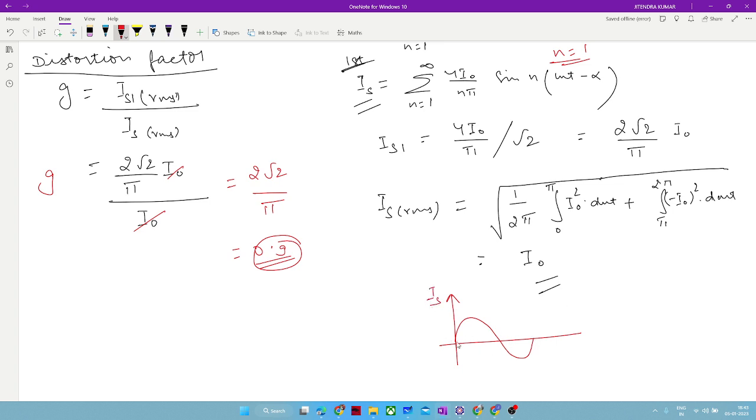But now your IS will not be like the ideal one. It will be kind of distorted. And this kind of distortion we generally limit with a hysteresis controller. So we limit it to a band, and beyond those bands it will not affect. So that is one approach.